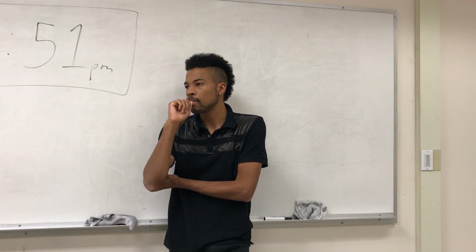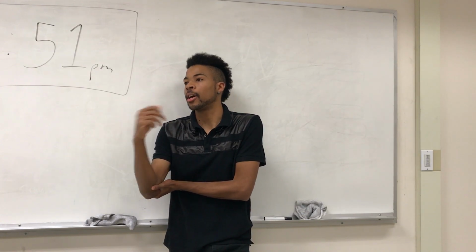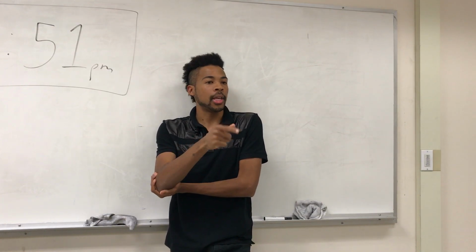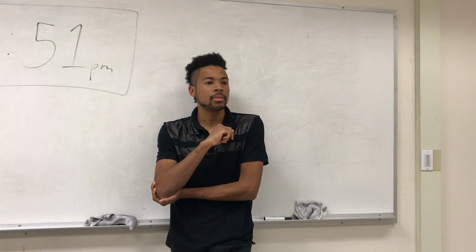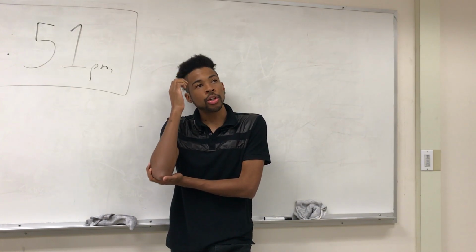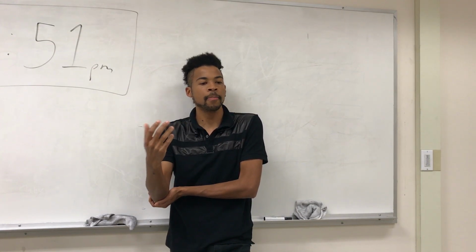What did you say? Strobe. Yeah, we can have a strobe. So effectively, like an edge-triggered interrupt, or just a single pulse. There's also, yes, a strobe interrupt is an edge-triggered interrupt. There are some interrupts that look just for the pulse to occur, and once it goes high and then back low, then they'll occur.